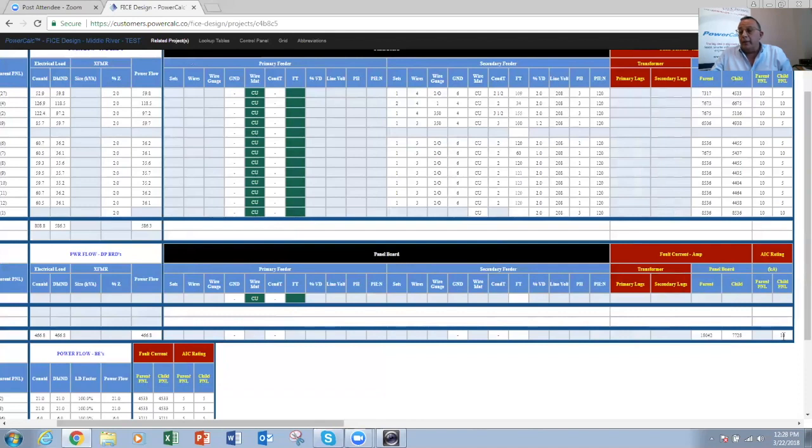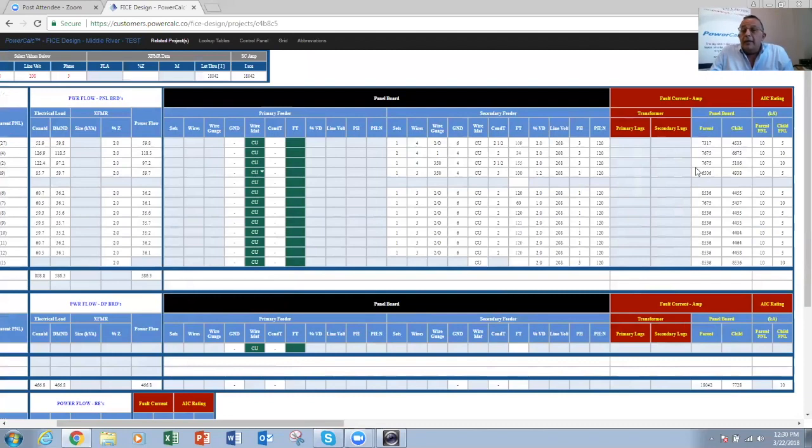Regardless of that, the panel itself is rated for 10,000 AIC rating, 10,000 amps. So if we go back to here, like we show on the second panel, at the parent panel, it's 7675. It's supposed to be very close to the 7728. It depends on the conductor size and whether it's running in conduit underground, not underground, all that stuff. But it's very close. Then it will consider that now the 7675 is the parent panel, and now the child, which is this particular panel, the second one, has an available fault of 6675. It will go ahead and select the AIC.